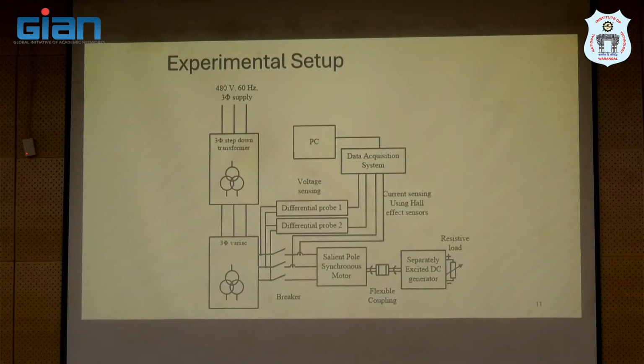Or the Hall effect sensors, the clamp-on type sensors, in some settings are battery operated. If the battery is low or drained, data acquisition might not be proper, and we might not even notice that the battery is drained. There might be an indicator, but you might not have noticed it.